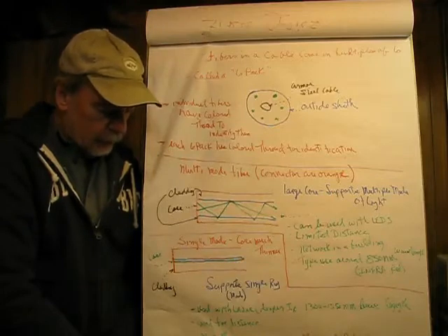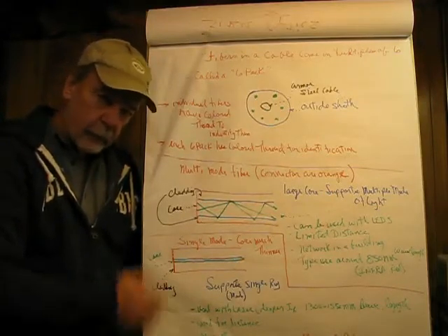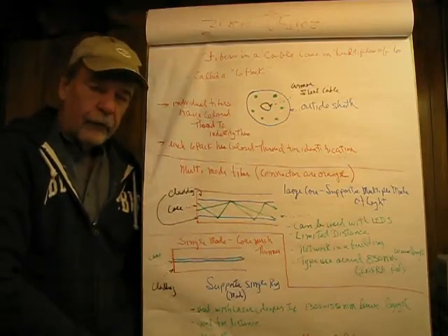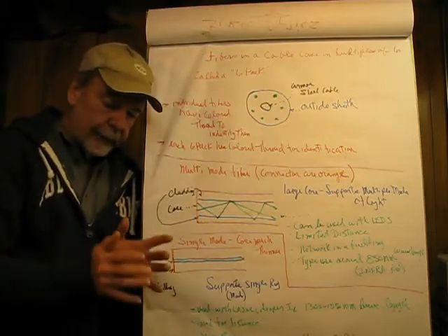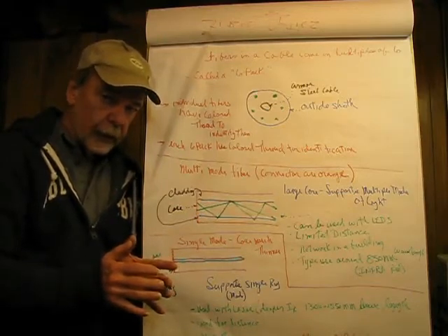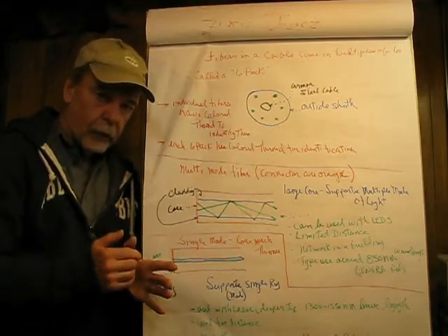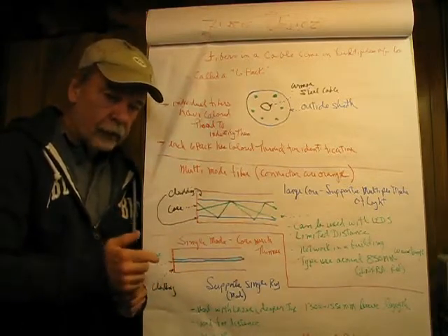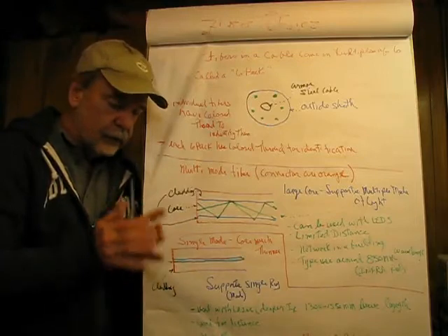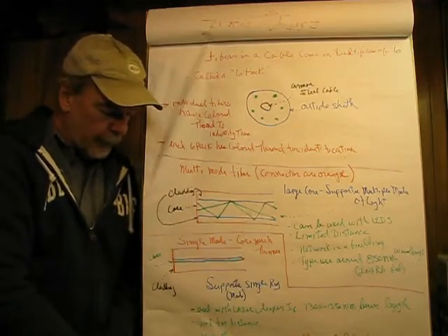If you're going cross-country, the optical signal, and there's loss in fiber cable, of course, is not amplified. The receiver gets it, and it's called a repeater. It knows what the signal should look like, so all it does is determine the ones and zeros, if you will, and then reconstructs them. It doesn't amplify them. It generates a brand new pulse and ships it on the way.